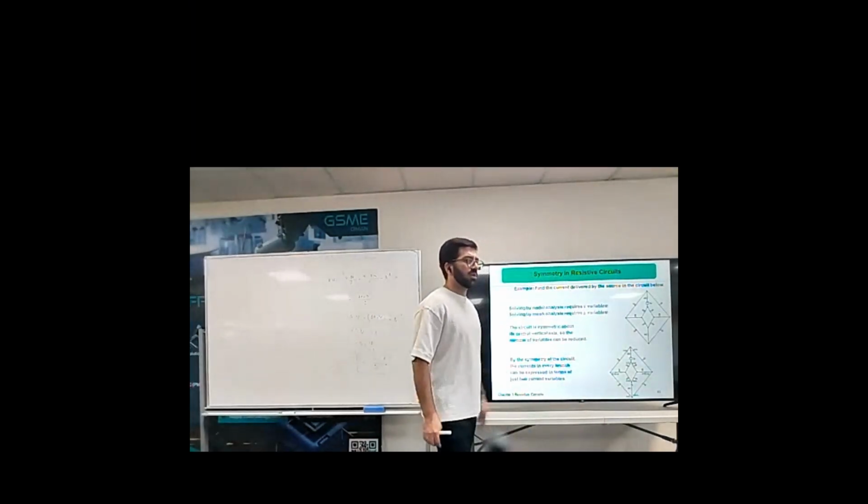we show all the currents and we just apply one KVL here, one here. It doesn't matter. You should apply KVL in two meshes. You cannot apply in these two meshes because they are the same. One here, or here and here, or even here. If you apply KVL on two meshes, you will have two equations, two variables. Easily you can find I and I1. When you find I and I1, that means you find all voltages and all currents.